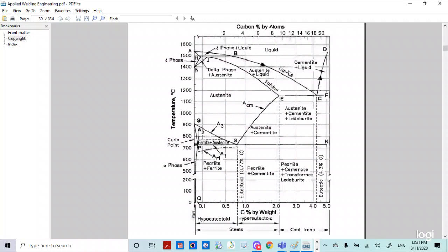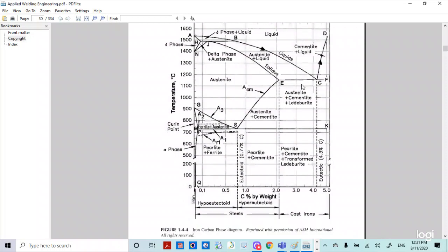So normally iron is soft, so to make the iron become hardened, we have to mix it with carbon. This diagram depends on the percentage combination of iron and carbon, and different kinds of steel can be produced. So this is the iron carbon diagram. This means how the iron and the carbon have to be mixed, from method to method, and then we can produce different kinds of steel. And page 53 is the steel table.